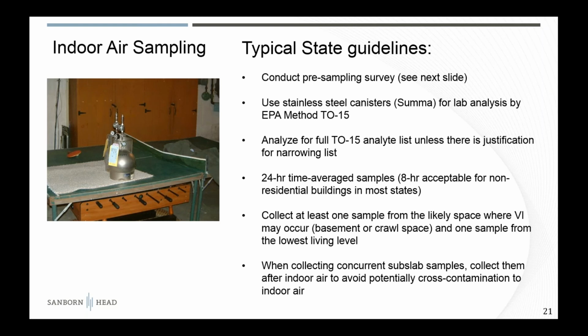Conventional practice for indoor air in residences is 24-hour average time samples, whereas in a commercial industrial space or a place where people are working, 8 hours is also typically accepted in most states. You want to collect at least one sample from the lowest level, the basement or the level that's closest to the ground surface, and one sample from the lowest living level if that's not the basement.